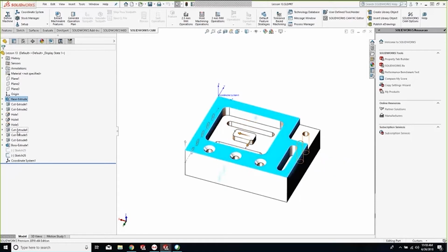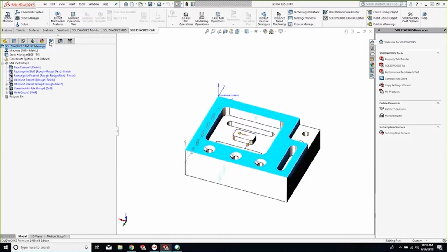You can see my holes, my extrudes, my cuts. But we are not using that information. When we run the automatic feature recognition, we are extracting our own features to apply toolpaths to. So if anyone out there is getting parts in from the outside, maybe they're not always native SolidWorks files. Maybe they're from whatever other CAD tool the individuals sending you files are using, we can still work with them. Even if you don't want to run FeatureWorks on it in SolidWorks, we don't need those features.